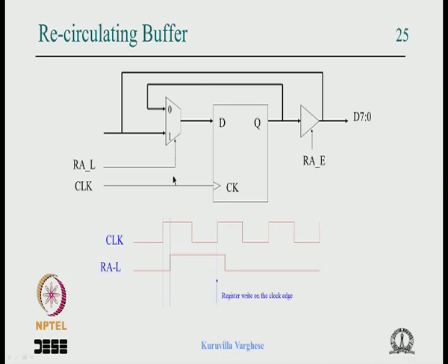It's not just one control signal, this is just like an enable signal for a register, but assume this is a counter. This could be an enable signal from the state machine, there could be a load signal from the state machine, there could be an up down signal from the state machine and so on. So this scheme can be extended, we have already seen it, but maybe it's the right point to stress it again.